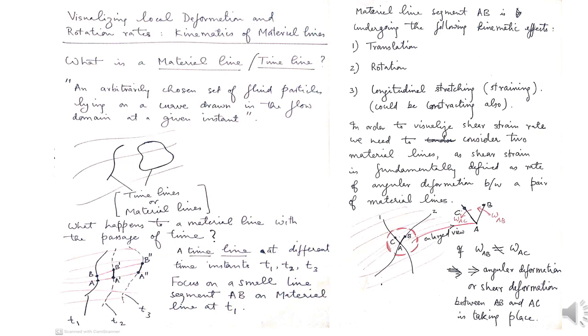It shows that I can construct them either as an open line, so that S-shaped line that I have shown on the left, and I can also construct a closed curve. Both are material lines or timelines. These are just curves. You can imagine you draw a curve at a given instant in the flow domain. So the curve will contain practically an infinite number of fluid particles over a well-defined shape, the curve that you have drawn. So this shape in itself is